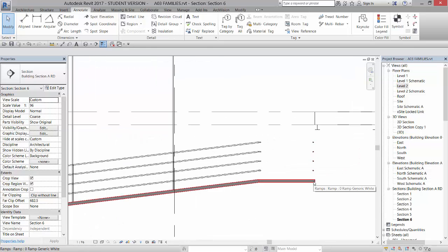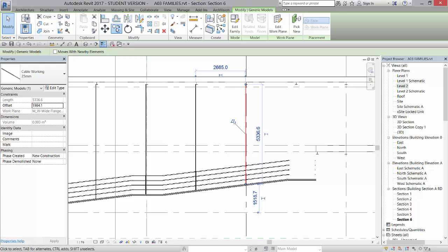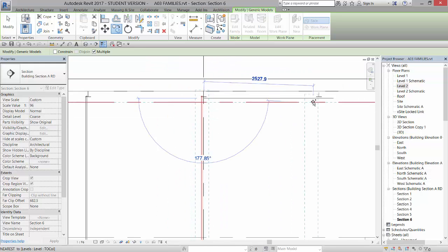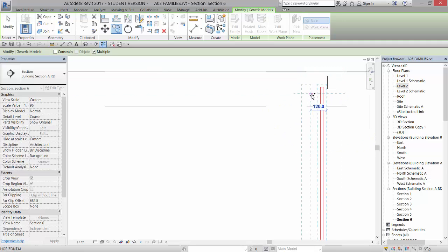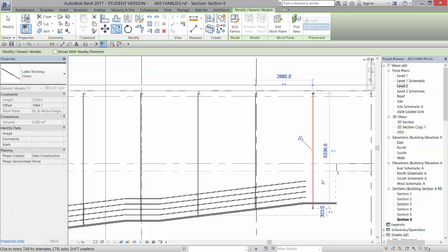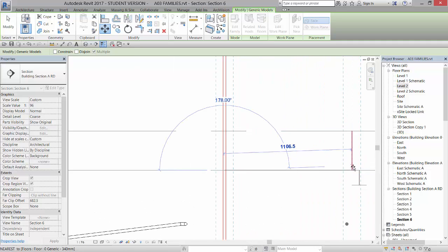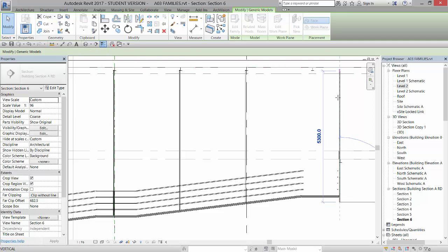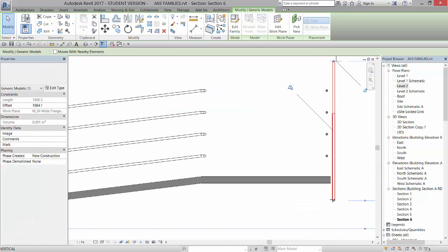This railing actually connects to that flange. So if I pick this and copy it right from center of there to center of there, right, we can come in and move it over from there into the correct place there, and just adjust the height of that to accommodate this particular instance.